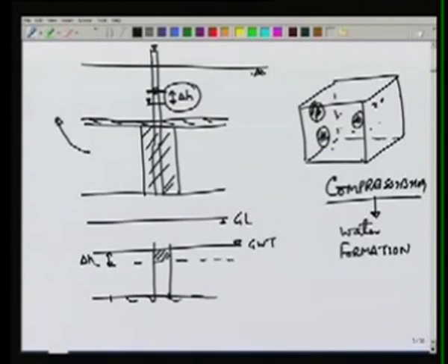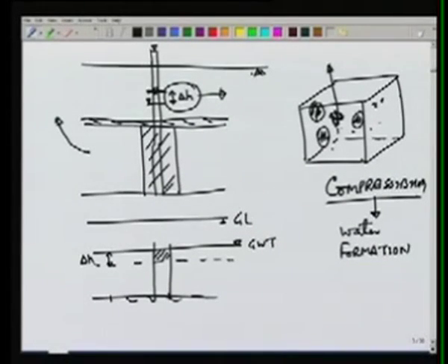When we lower the piezometric head, the water from this element, suppose it comes out of this element. Now this water is under some pressure which has been kept constant, but now it has been lowered because of this lowering delta H. So when we reduce the pressure, water will expand and therefore it will come out of this element.